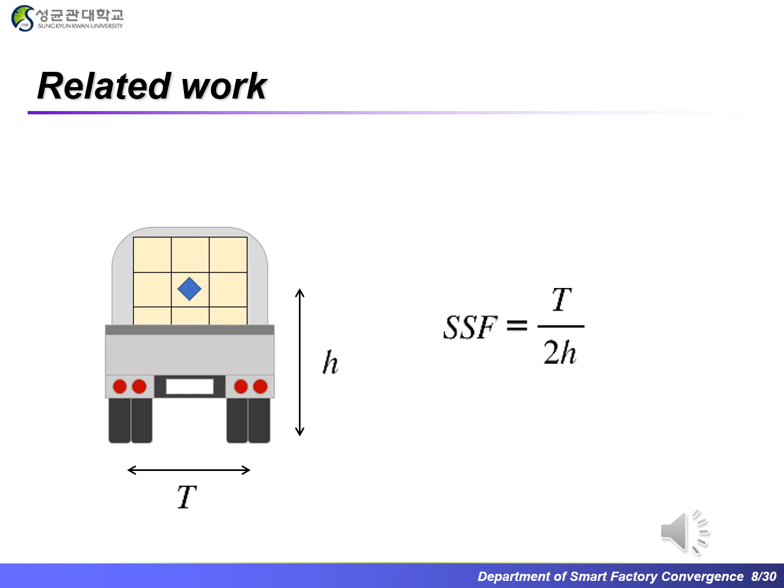The SSF of a vehicle is an at-rest calculation of its rollover resistance based on its most important geometric properties. Basically, SSF is a measure of how top-heavy a vehicle is. A vehicle's SSF is calculated using the formula on the right.